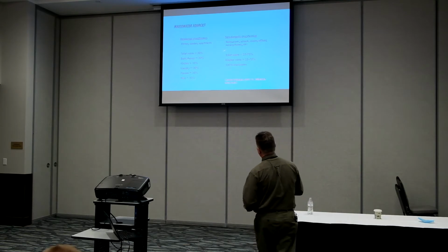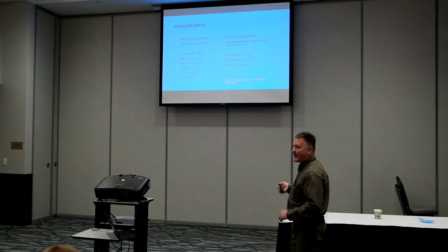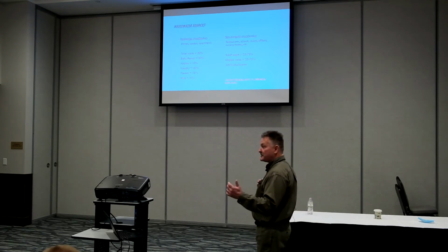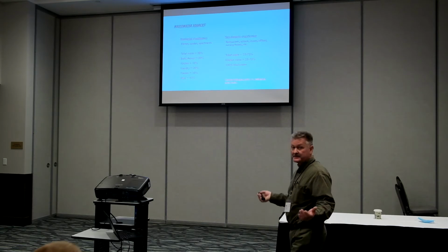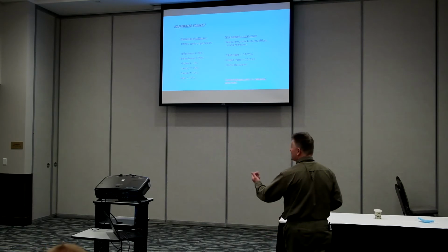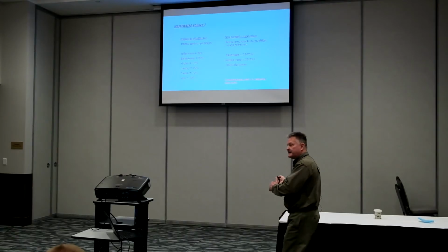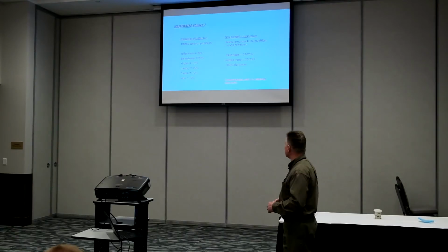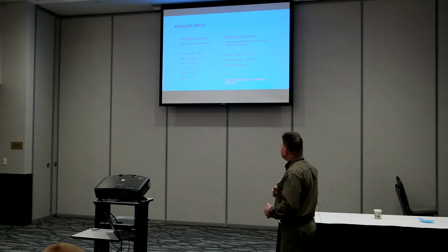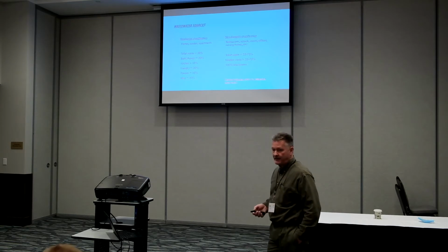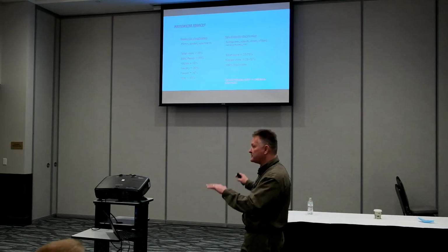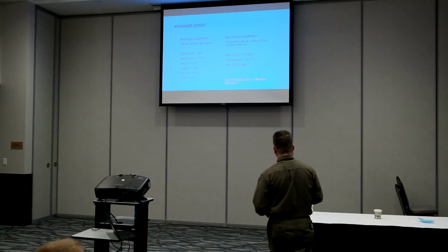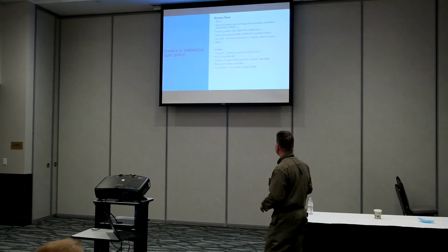Once we get into some kind of commercial application, we have a whole wide range. We can have 25 to 75% black water, or the same with gray water, or we can have 100% black water, for instance, on an office building. And all those are going to have different characteristics that can affect the design and the performance of that system. Typically, especially with kitchen waste, which should be considered gray water, that's going to be very high in waste strength. We'll talk about waste strength numbers and what those mean. So there is a difference between commercial and residential gray water.